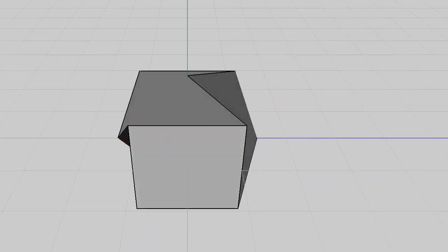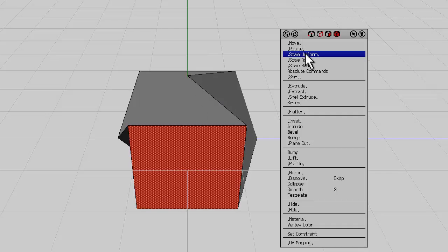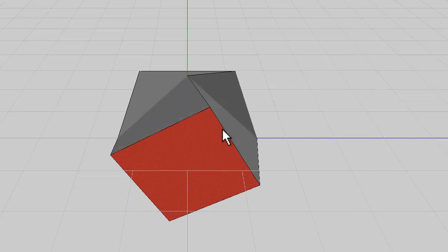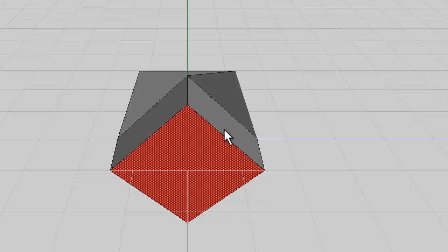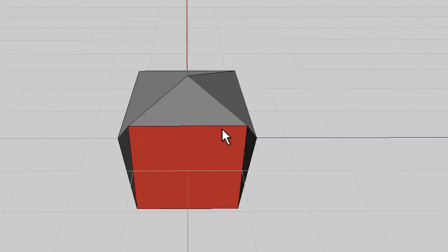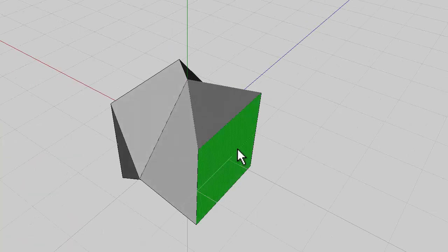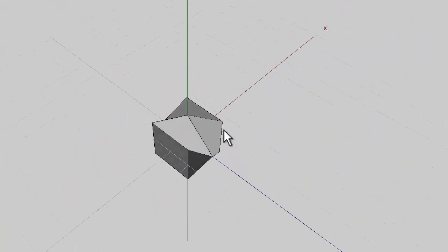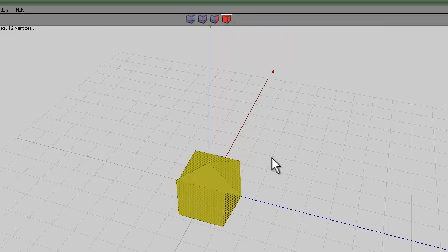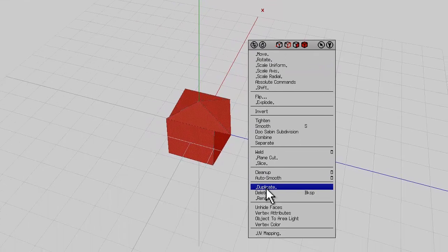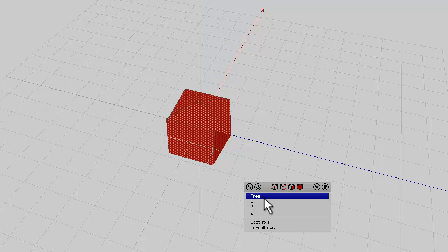And then select an end, so press space to deselect, select an end, rotate x-axis again, so rotate it to 45 degrees so it matches, then continue the rotation so you've managed a 90-degree rotation between this end face and that end face. Right, we're going to need a few of these, so select the entire object and use the duplicate tool, and you want to move it along the other axis, so the z-axis in this case. Y-axis would do, but not the x-axis.